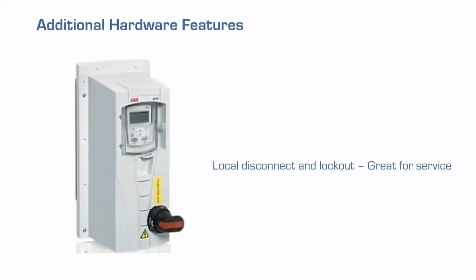Okay, so it's some additional hardware here, Adrian. I'll let you take this one away. Okay, so one of the most popular features we can add on a VFD is a local disconnect. This is great for service people. Instead of having to go back to whatever MCC is feeding this VFD with power to lock it out, they can just turn this handle, put their lock on, and now it's safe to service that motor.